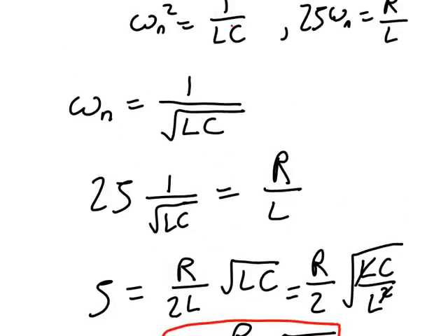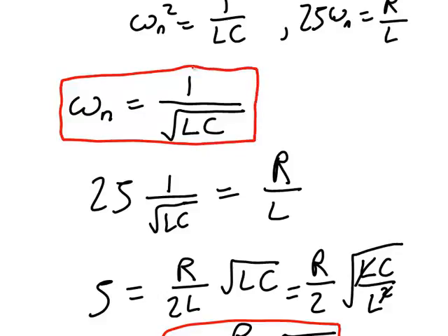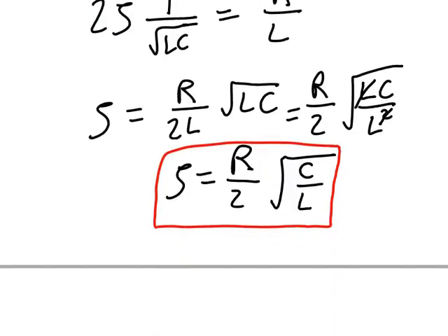Similarly, you can also set the natural frequency of the system by setting the values of L and C. Setting the natural frequency of the system will be important if you ever expect your system to receive a sinusoidal input. In that case, you would want to make sure and set L and C so that the forced frequency of the system doesn't ever overlap with the natural frequency. Especially if zeta is much less than 1, you would cause some problems in the system as the system begins to resonate.